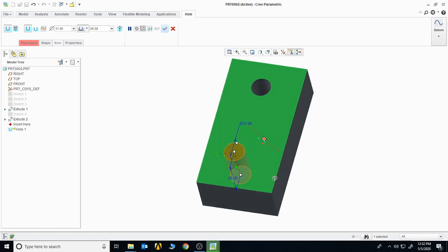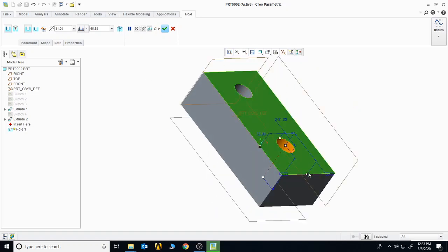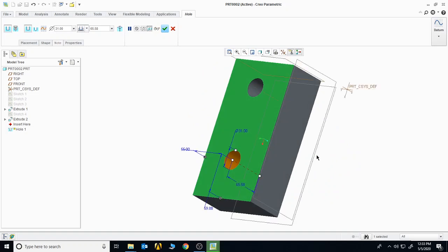Once you place it here, you can see that there are two green boxes and three white boxes. The green boxes are used to define its specific dimensions from a certain point. Press on this green box and place it to a side from which you want to get the dimensions. Again, click on the green box and attach it to a certain side. Now you can edit the dimensions from here. If you want to place it at 50 or 55 inches from here, simply enter the dimensions and it will move accordingly. Same is the case with the other side. You can change the dimensions of that.